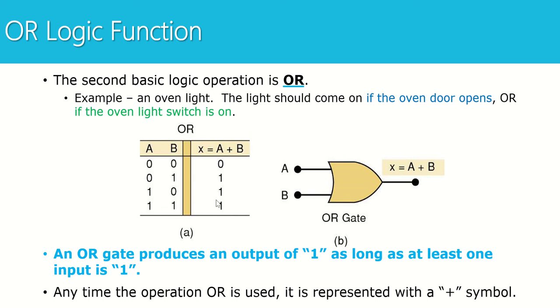Why isn't 1 plus 1 2 right here? Well, that shows that they're thinking about that plus sign as addition when that's not what plus means in a digital realm. Within the digital world, plus means OR. So I'm not saying 0 plus 0 equals 0. I'm saying 0 or 0 equals 0.